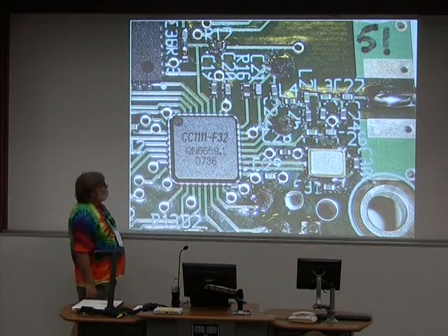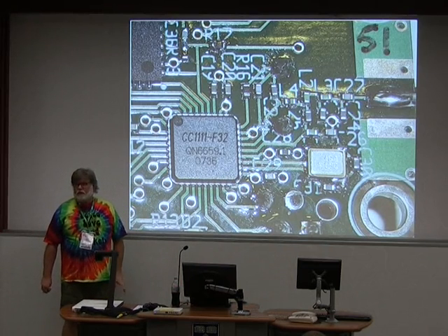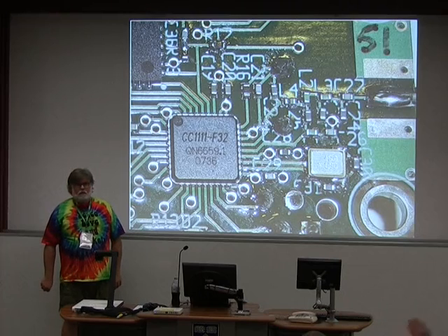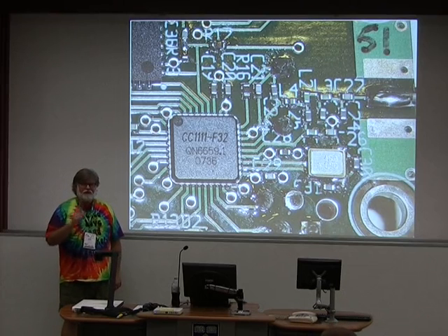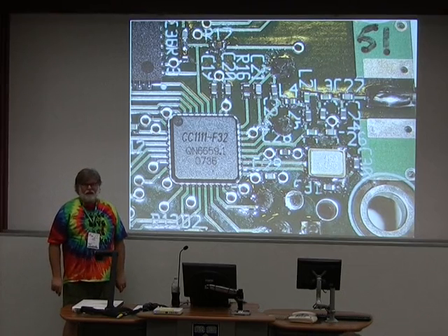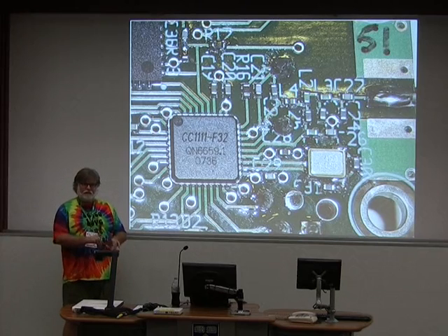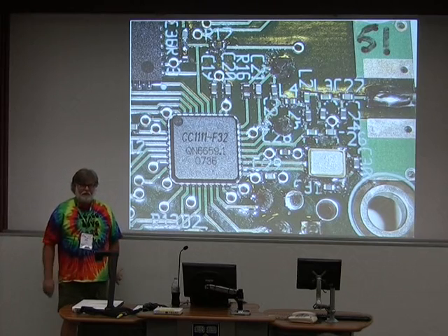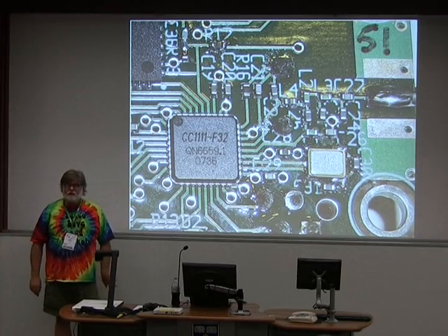There are a couple of other interesting little tricks. How many of you have ever actually designed an RF board of any kind? One of the tricks to making them work is to not put a whole lot of inductors adjacent to each other, because they'll couple to each other and mutually interfere. It turns out that even in 0402 surface mount parts, this really still matters.